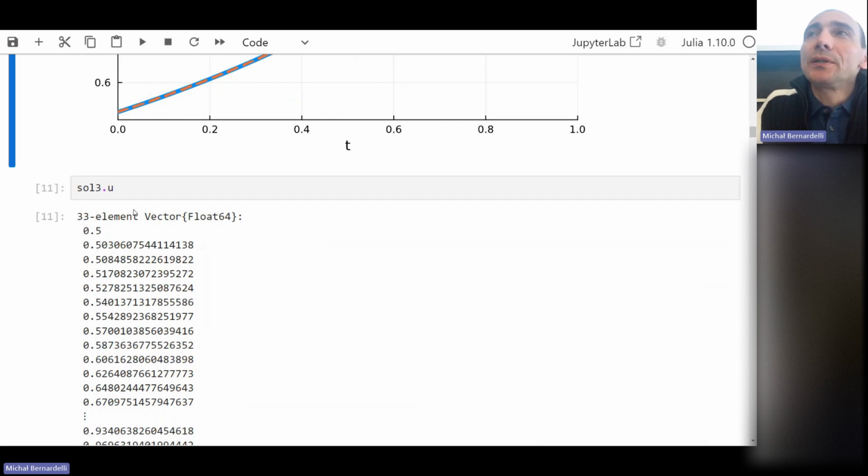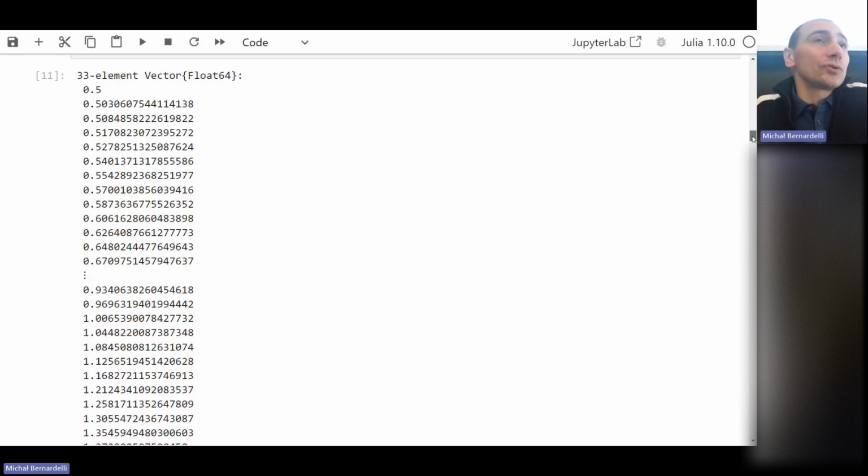And if you want to see how big the vector is, how many nodes were used to achieve this kind of accuracy, 33. By default, you've got 5 in this particular case, of course. If you want lower accuracy, you can use 4 or 3. But if you use 50 or something, you are so close to the solution that absolutely no one needs better accuracy than this. And remember that this is a smooth solution and an easy task. If you've got more complicated problems, then the number of nodes will be, as we will see in a minute, not 50, but sometimes thousands. This is why it needs time to compute the solution. So you can get access to any vector, and you can also easily interpolate the solution by getting the solve from it.